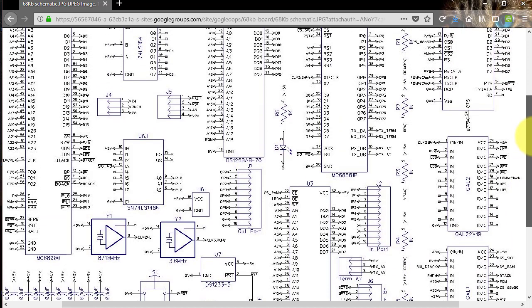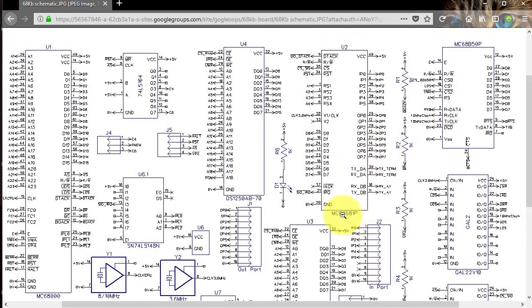Now if we look at the comms or UARTs, in one of the designs you can use the 68681, and it's got 2 serial ports on it together with input port and output port, and it's using the low-end data address lines for its communication, and needs that 3.6 megahertz signal, and it needs the 4 address lines to be able to look at all the registers that it needs. And there's also all these other control lines that connect to it, like the reset, the chip select, the read write, and so on. Okay, that's about enough for that one.